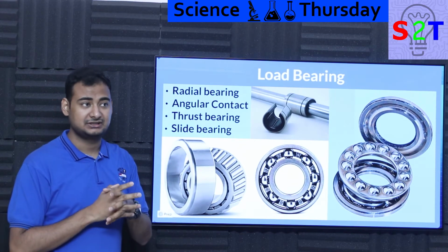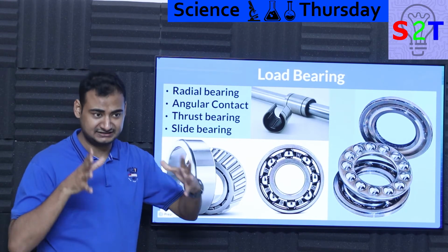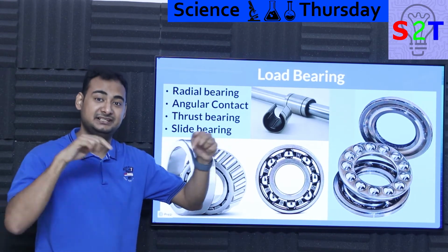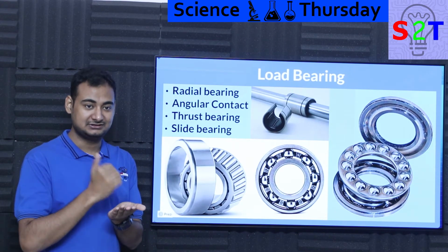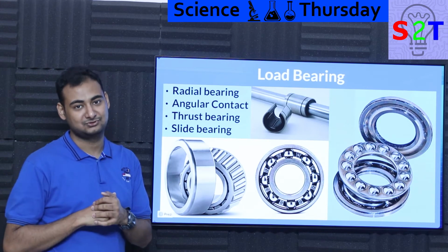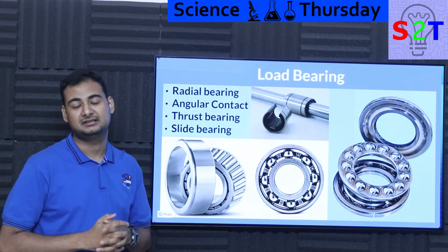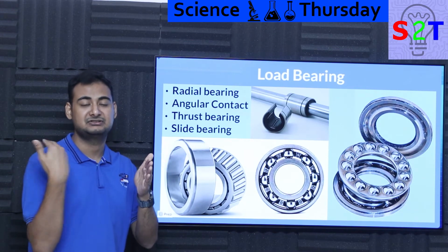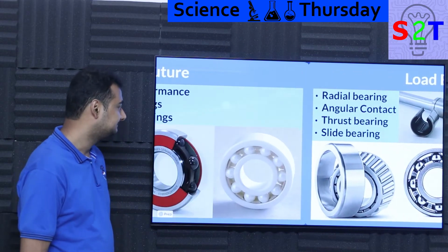You can have a scenario like steam turbines, which have a surprisingly large number of bearings. They have a bearing assembly with multiple types of bearing in it. This bearing section is handling lateral motion, this bearing section is handling up-down motion. And other bearings would be specifically built just to handle pressure, so it can seal up against a system. So that's how load bearings are handled.